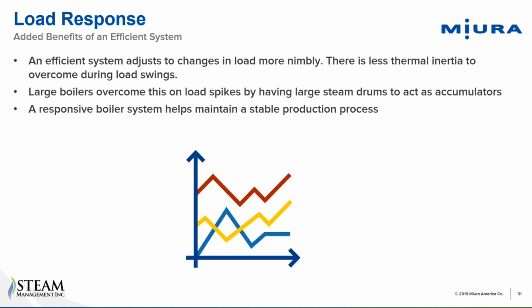So if you can maintain that constant steam pressure, if you're going to maintain constant steam temperature inherently, that's going to help maintain a stable production process for whatever you're using the steam for in the facility.